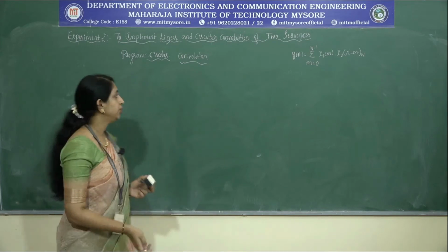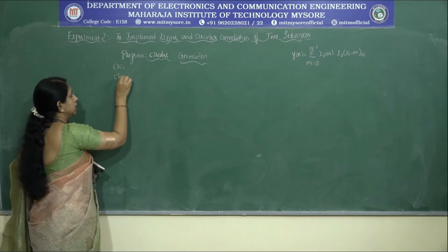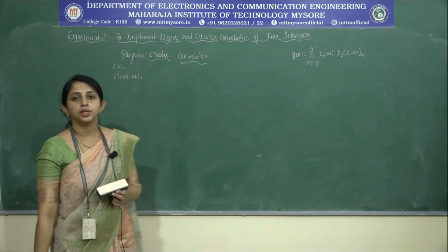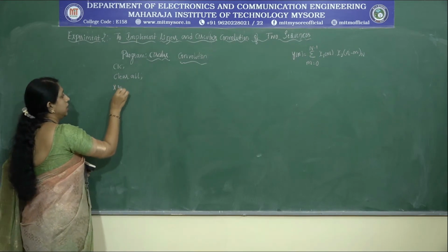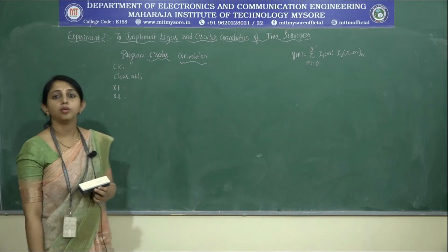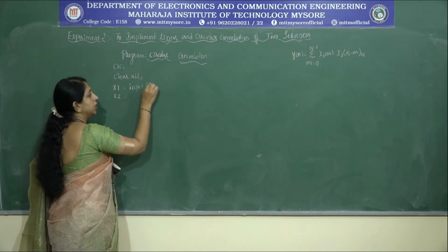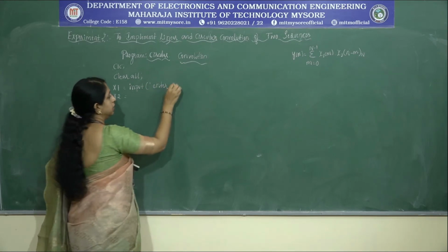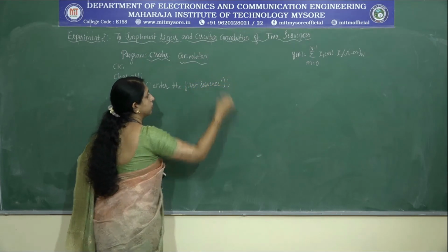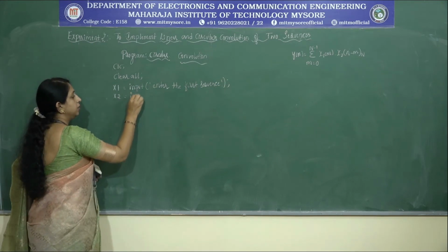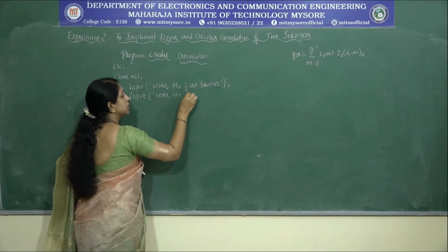As we know, you need to start every Matlab program with clc and clear all. Then, here also for circular convolution, we have considered 2 sequences, x1 and x2. How to enter these 2 sequences? Again through the input command within a single inverted quote, right? Enter the first sequence. Then, similar to that, go for a second input which is assigned to x2, input of enter the second sequence.